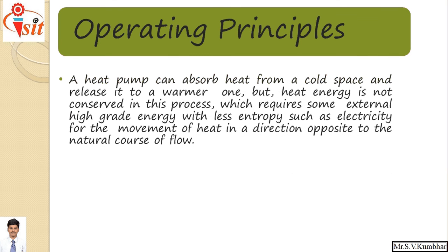So coming to operating principle, as we have already seen, in a heat pump, heat is continuously extracted from the low temperature body. That heat is supplied to the high temperature body, provided that the temperature of the hot body is maintained above atmospheric temperature. So a heat pump can absorb heat from a cold space and release it to a warm space. But heat energy is not conserved in this process, which requires some external high grade energy, that is electricity with less entropy, for the movement of heat in a direction opposite to the natural course of flow.